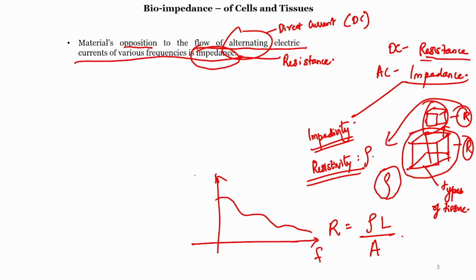Frequency, impedance. Now, at 0 frequency whatever impedivity value we get, ideally that should be equal to the resistivity, correct, because at 0 frequency the capacitive reactance, inductive reactance are not taken into consideration basically. Basically the capacitor, if there is indeed a capacitance in the path, it will act like an open circuit. So the zero frequency impedance value is the resistivity basically, provided the circuit does not have any capacitive components.